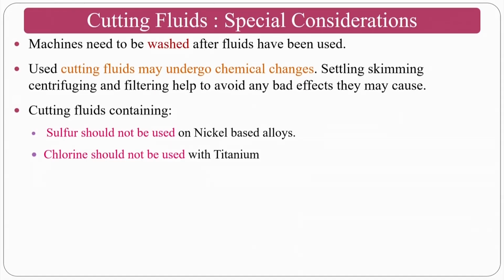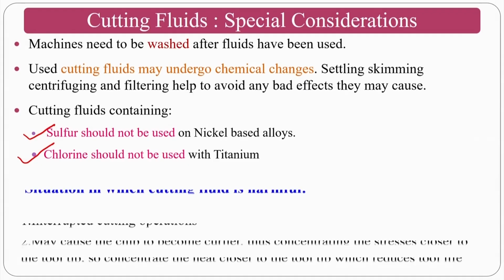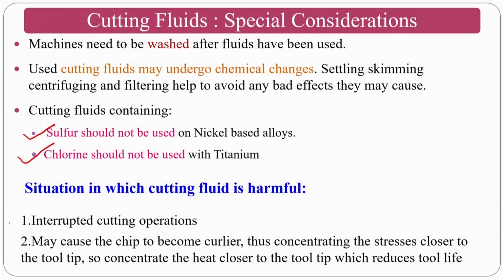Cutting fluids containing sulfur should not be used for nickel based alloys, and chlorine should not be used with titanium, because it is chemically reactive. Cutting fluids are harmful. Normally in interrupted cutting operations, the pressures or forces of the cutting or machining will come suddenly, so a sudden jerk will come. For that purpose, you should be very careful whenever you are using interrupted cuts and curly chips and other things. So, you should be very cautious about these types of things.